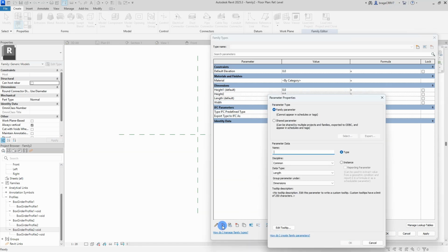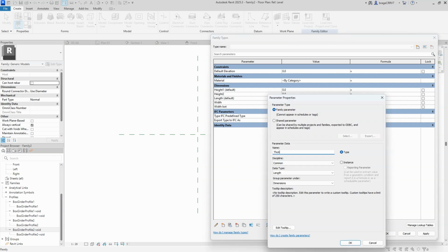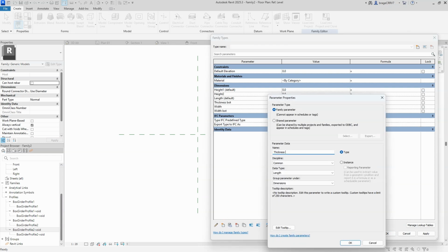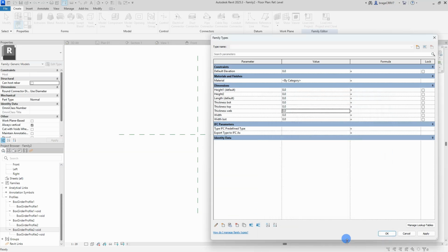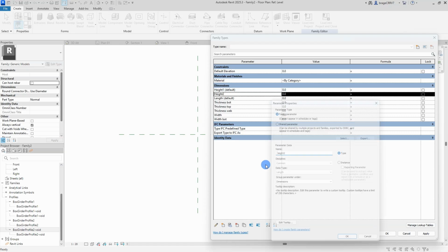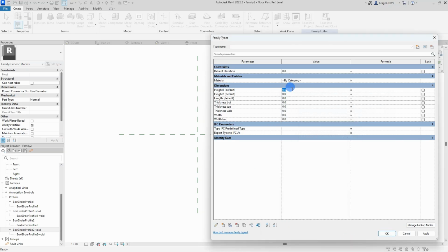The main difference is that I'll be using 2 separate height parameters, height 1 and height 2, to represent the differences between profile 1 and profile 2. Although we could introduce 2 different width parameters as well, let's keep this example simple. Also need to type in some numerical values, or there will be an error when linking them to nested families.